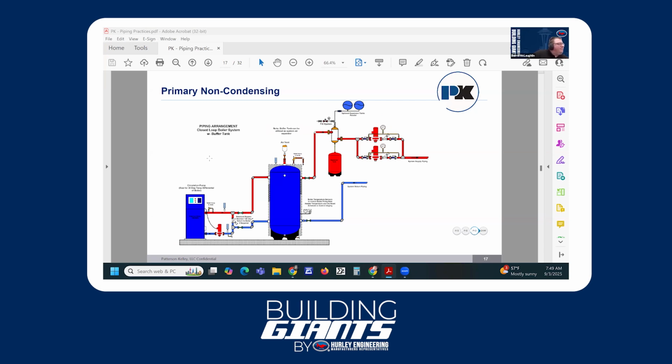We've talked about swing tanks and buffer tanks for condensing applications in primary-secondary. Here we've got a primary only setup, and we've got a buffer tank here for a low mass system. Just like we had a swing tank on the heat pump, we're using a buffer tank to control the swings in load on this system. Again, we've still got our three-way, it's not a valve here, but we do have a bypass return to protect return temperatures to a non-condensing appliance, even though this is a primary only system.